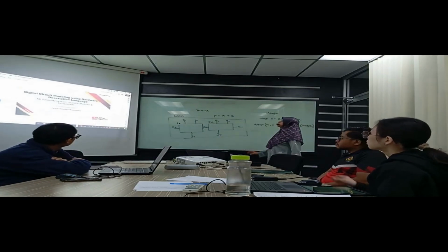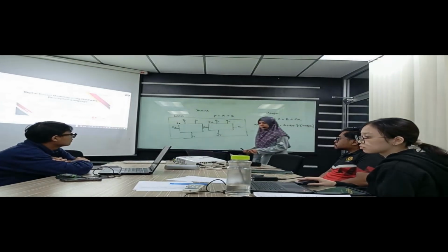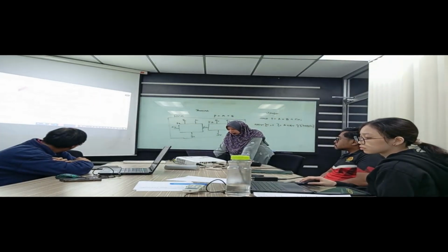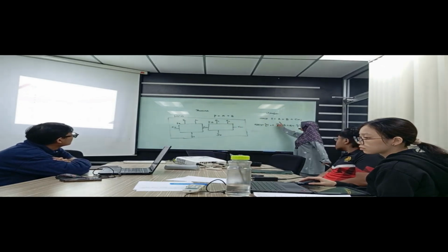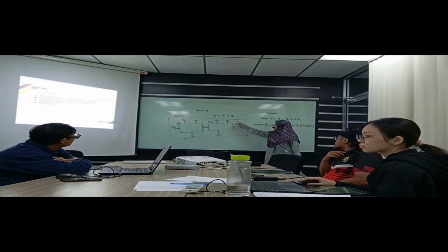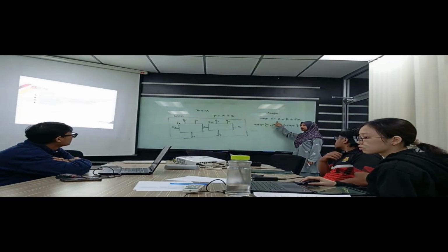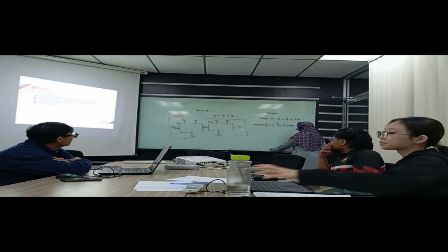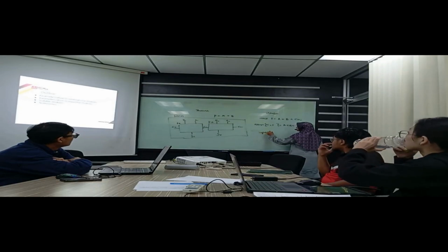Okay, so we go to the parameterization and scalable modules, and let's measure that. The concept of parameterization: when you design this, you already assign the value as a scalar value, meaning you already declared A and B as 4 bit directly.